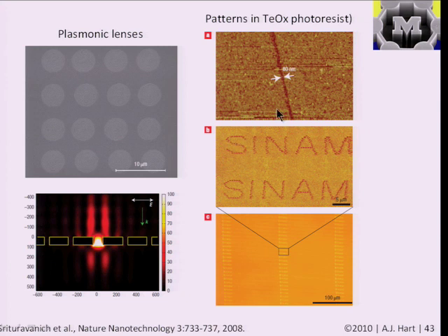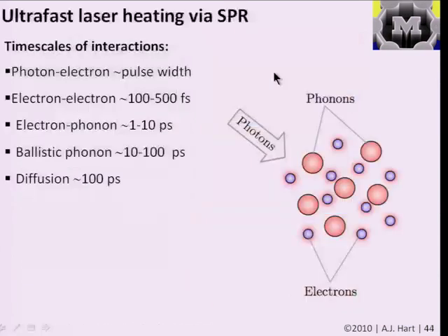Incidentally, at the level of demonstration, it's possible to use advanced optical lithography as used in the semiconductor industry to achieve dimensions smaller than this, but this is a really interesting demonstration where this type of interaction, the interaction between the beam and a metal mask because of the near field, is what causes this patterning ability. And they made structures in grid patterns over relatively large areas, and were able to write dots by pulsing on and off and coordinating the motion. And then this is the finest line that they showed in their paper a couple years ago.